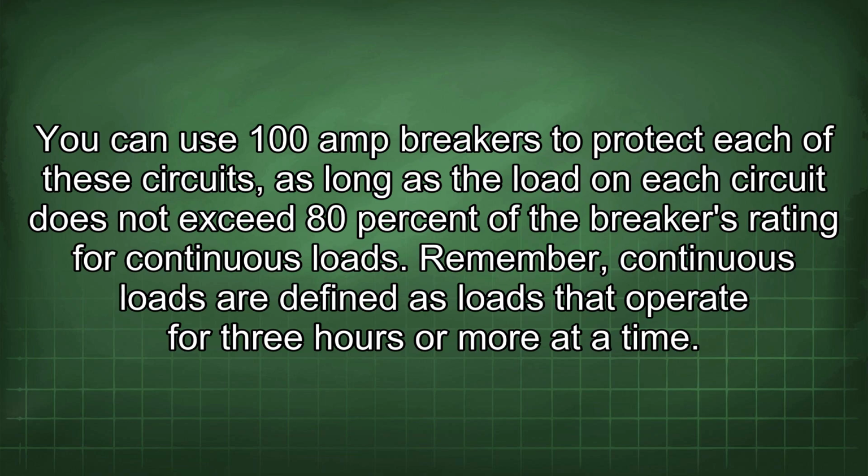You can use 100 amp breakers to protect each of these circuits, as long as the load on each circuit does not exceed 80% of the breaker's rating for continuous loads.